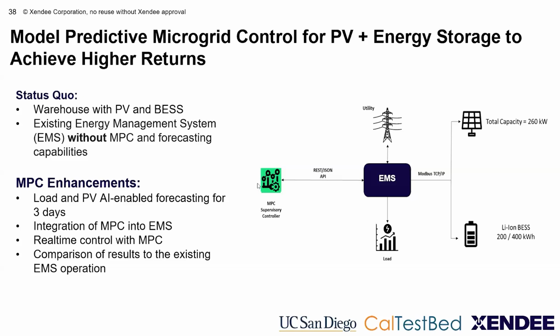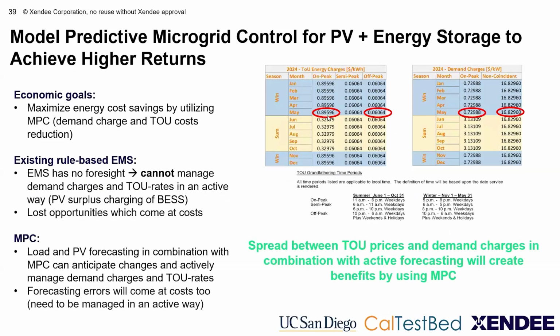And here we are riding on existing hardware controllers. So we already have a hardware controller for the microgrid in place, which does some basic functionality. But on top of this, there could be a software-based controller, like this one with an MPC, to do the forecasting and the smarter prediction. And this works because of different electricity prices, for example. This is why I said most microgrids really benefit from this cost management. If you run a microgrid in Africa for electrification, you don't have this complexity and you have different objectives than what we have here, for example, in the United States.